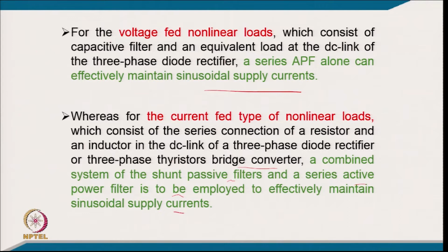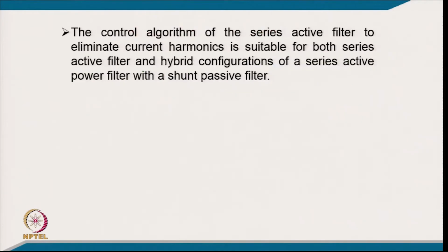So, that load is not really affected by that, but a series filter will be forcing the entire harmonics current into the shunt passive filter. So, series filters are typically used for a small rating in those applications also.